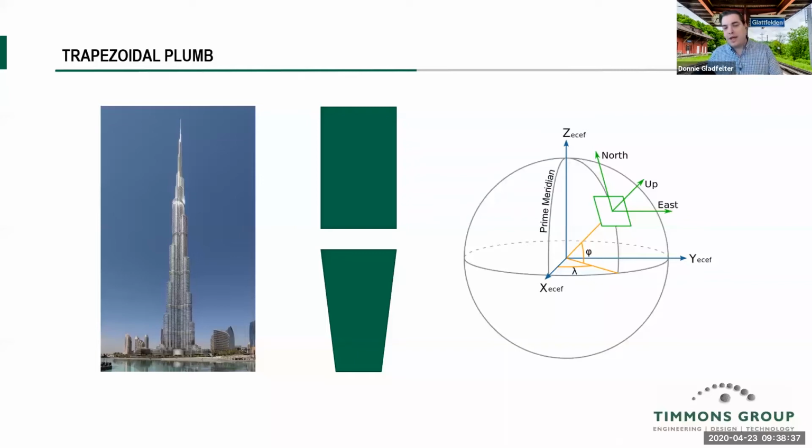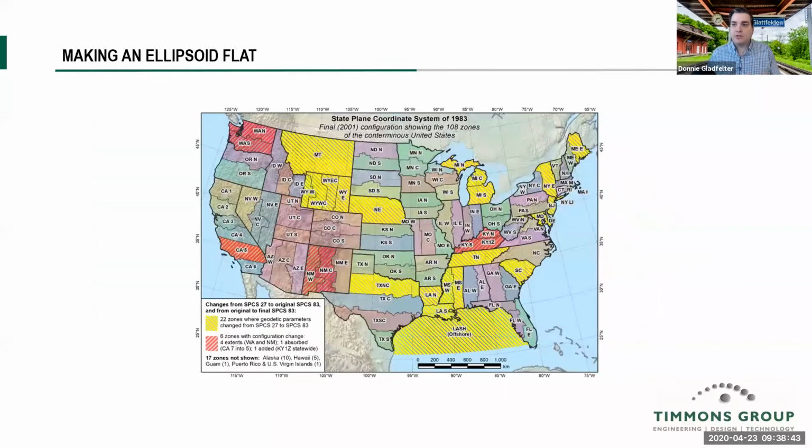And so with that in mind, as we take a look at how we address this on the civil side, again, we create models too, but everything that we do is going to be projected to a geographic coordinate system. Now, the prevailing system that is still used today is something known as the North America Datum of 1983. It's been updated a few times. There's actually some new datums getting ready to come out. And again, this is kind of the map of the United States, all of the various coordinate systems.